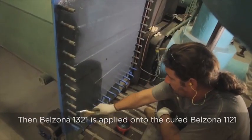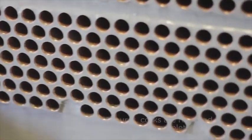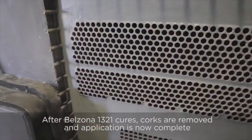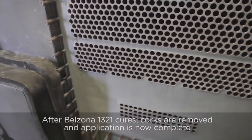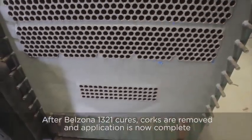Once both of them have cured, you can then finally remove the corks from the system and dress back the coating to give you a nice flush finish where you've prevented the liquid from contacting the surface, and you've also isolated the tubes from the tube sheet face, which means you've prevented any type of corrosion from happening in the future.